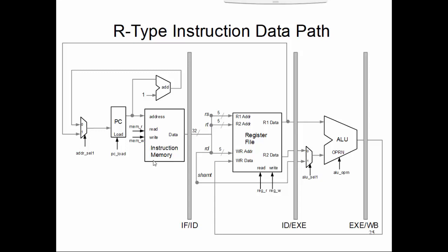Now, while instruction 2 is being fetched, your register fetch is done for instruction 1, and at the end of that cycle, all the data produced from this stage goes into the execution resources via another bunch of registers, placed at the junction of your instruction decode and exe phase.